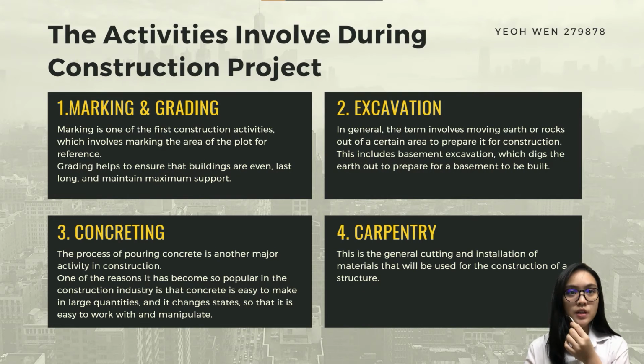There may be particular circumstances when something is being constructed that would require a slight incline or decline to the base surface. In this case, it would be very important that the incline is exactly the correct angle. It is a matter of safety and plays a major role in construction management. Grading uses big machines to help ensure the space is level or at the appropriate angle that it is supposed to be.